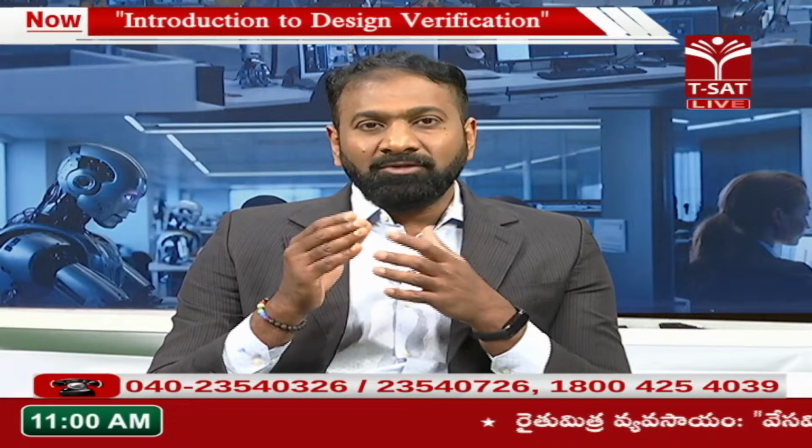In case of formal verification, we use mathematical models to prove the two versions of the design are equivalent. And also, let's say you're doing some bug fixes in your RTL design. You found some issues, and the RTL designer is going to do some bug fixes. Now, how can I say that the reference design, my golden design so far, which I believed was correct, but once I found the design bug, I fixed it? So the design version has changed, right? So now I have two versions of the design.